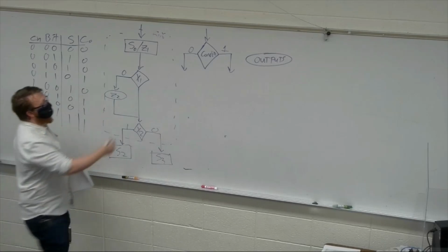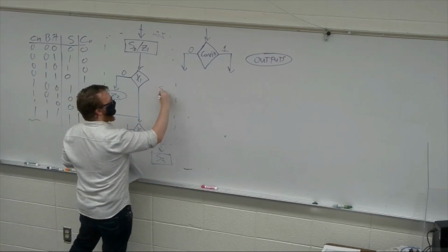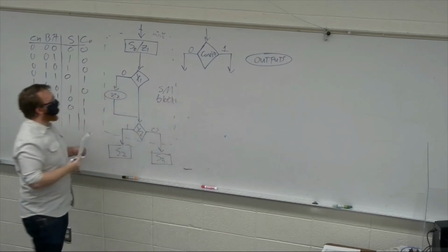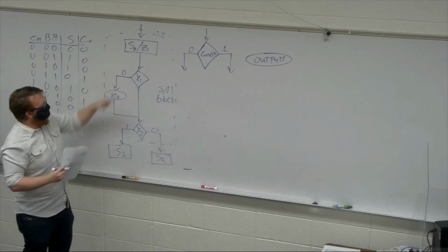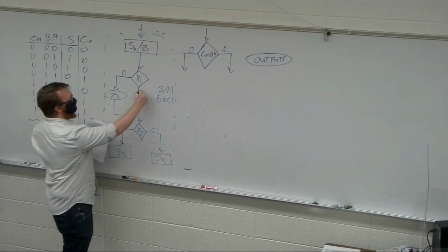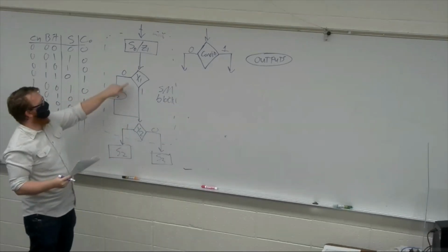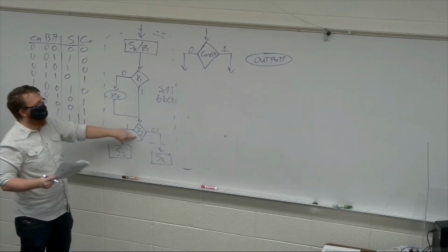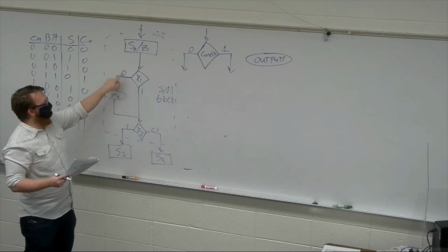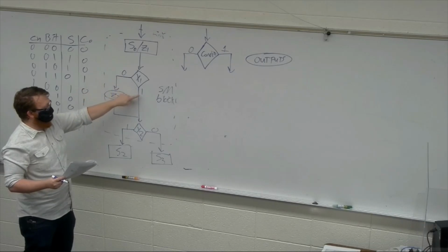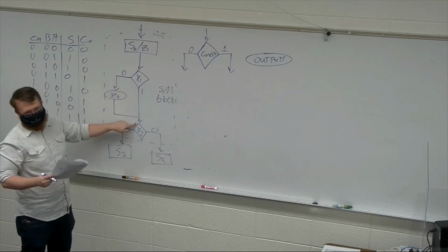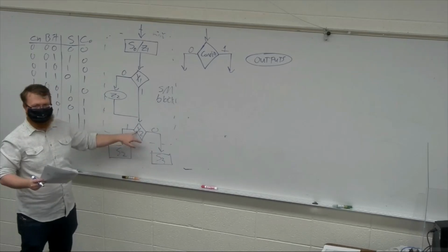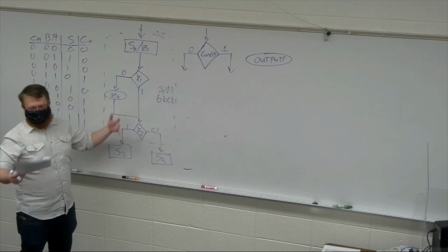Okay, so the dashed lines are SM blocks. So it's just coming down, makes a decision on if I go 0, assert Z2 and move on to this condition. If I do, it's 1, come down. Regardless, I'm going to move to X2 and either move to state 2 or state 3, depending on the condition X2. This is all it's going to do.